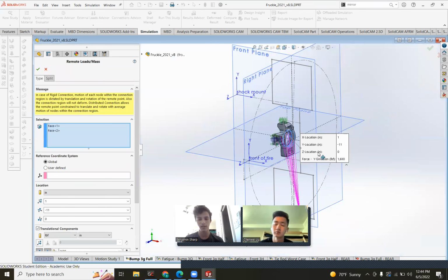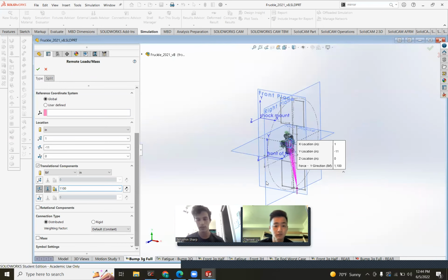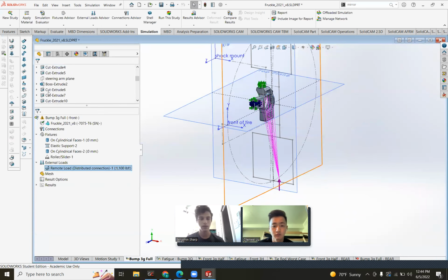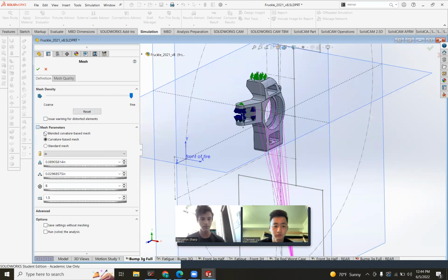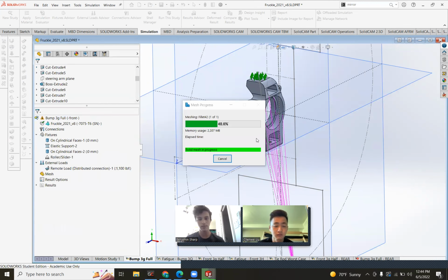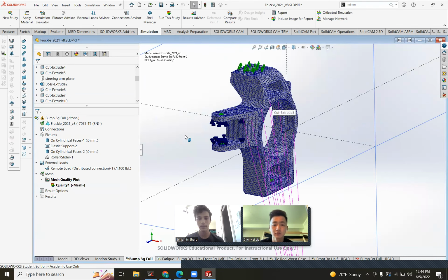And this is a much higher load. I was actually able to use 1680. So let's instead do 2 Gs for the full car. But this is an upward load right there. In the mesh, I'm pretty sure I just did a curvature-based fine mesh and it was enough. This is easier FEA. This is more like traditional FEA. Oh, that's very fine. Shoot. All right.